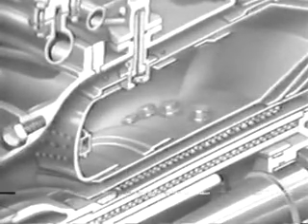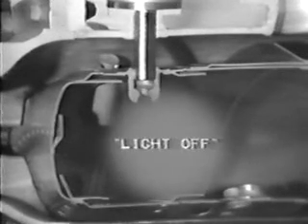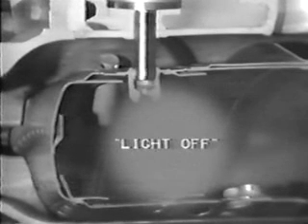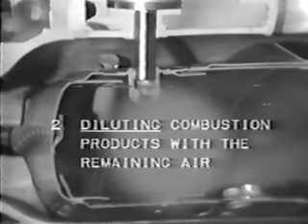The combustor has one primary function: to produce heat for the expansion of air. It does this by releasing chemical energy which is stored in the fuel. Ignition occurs when a spark is applied to this air-fuel mixture and burning begins. This is often called light-off. The total combustion process is divided into two steps. First, the burning of part of the air with fuel, and second, diluting the combustion products with the remaining air. It is in this second step that all the air becomes heated, causing rapid expansion, which is used to drive the turbine.